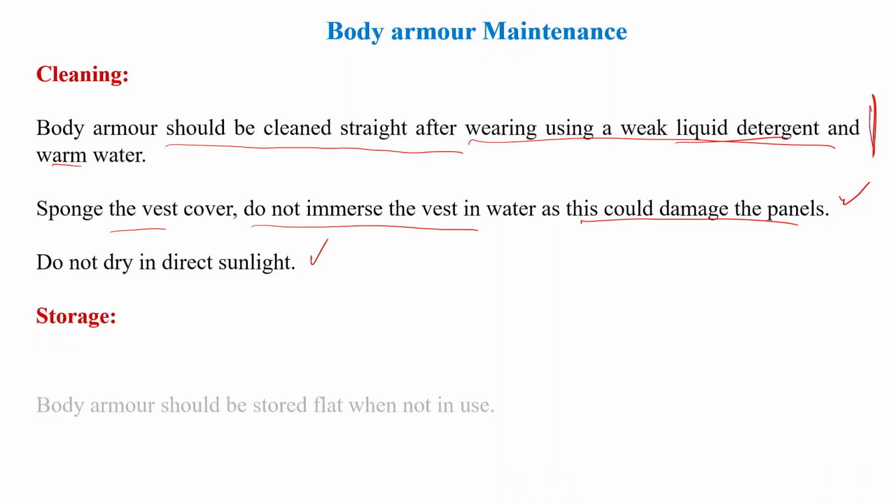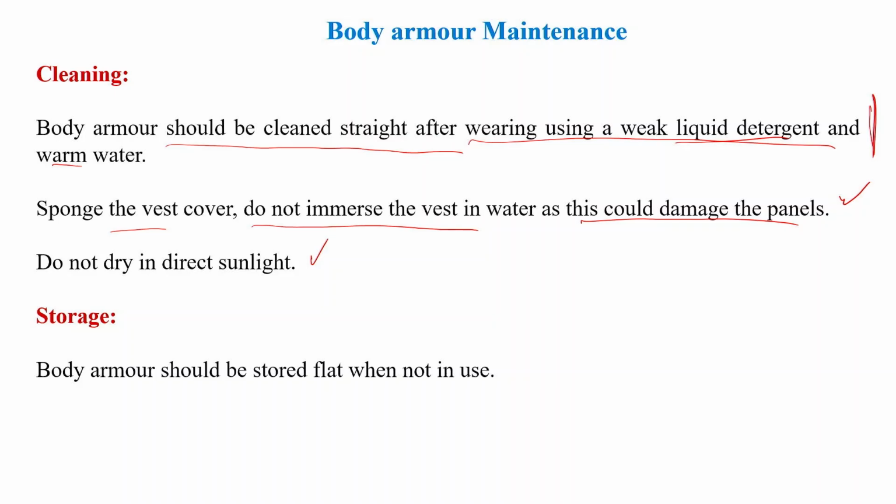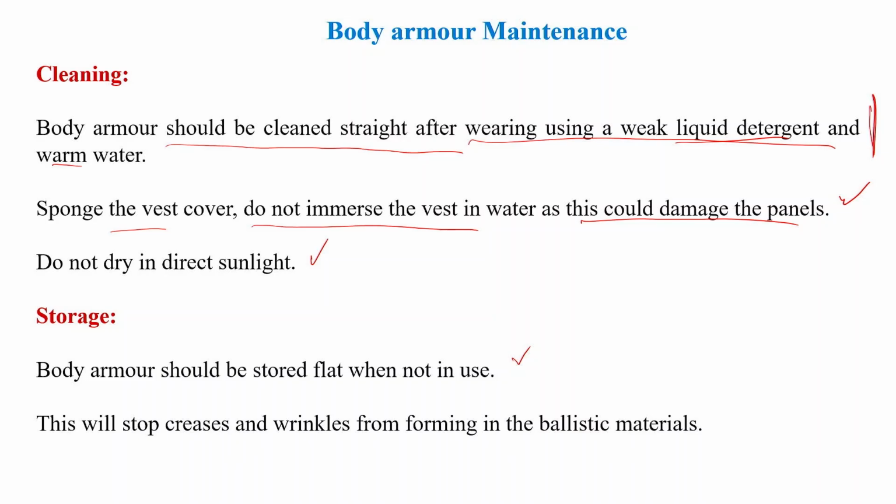And storage: body armor should be stored flat when it is not in use. We should not fold it, because if we fold it, at the crease point some damage may take place. So, we should always keep it in a flat position. This will stop creasing and wrinkle formation in the ballistic, and in the wrinkle or crease portion there may be some damage to the fiber due to the high crease. So, that should be avoided.